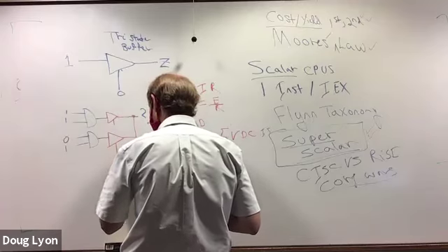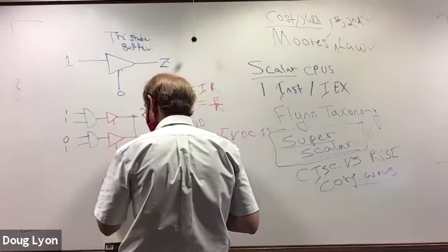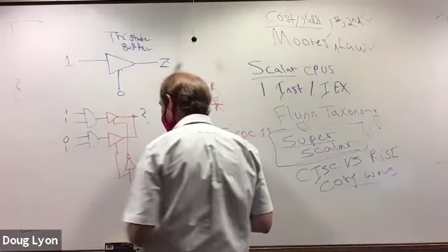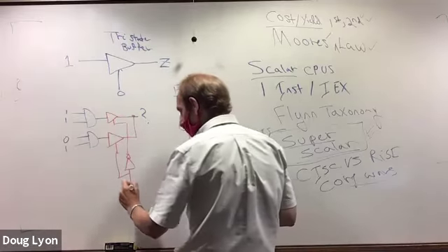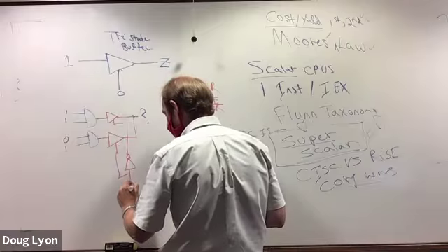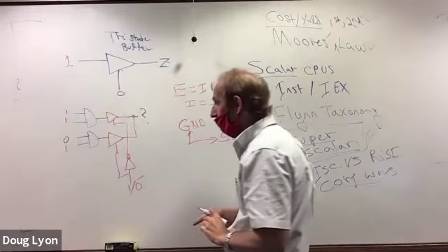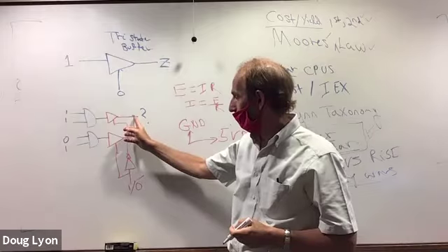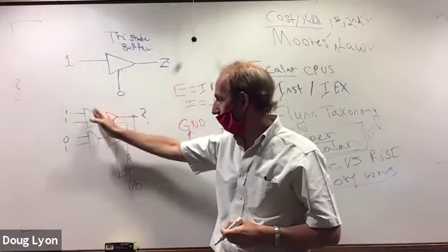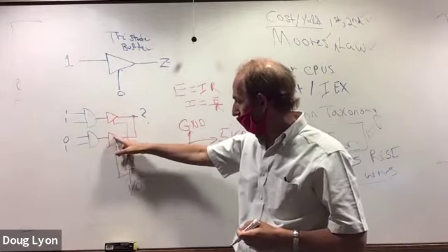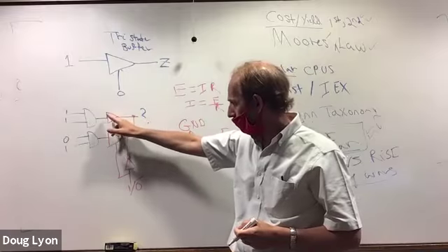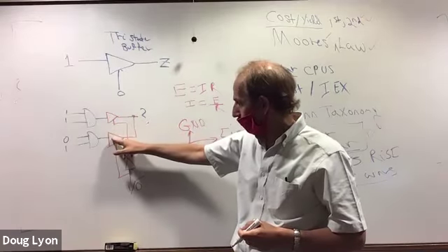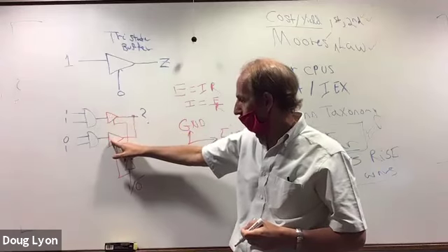Right. And the inverter, there's that. So now you can choose device 1 or 0. And that allows you to choose who's going to drive the output line, either this guy or that guy. When this guy is on, this guy will be in a high impedance state. And when this guy is on, this one will be in a high impedance state.